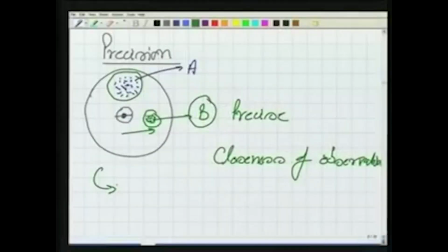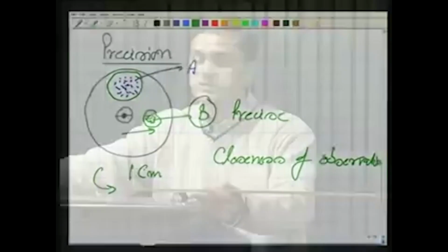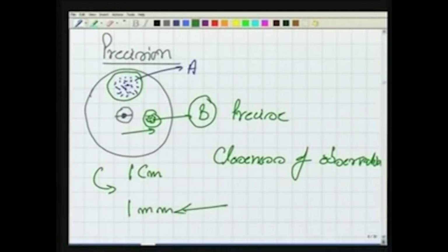Another example, well, in this scale, if the least count of the scale is 1 centimeter, you are trying to measure up to 1 centimeter, and then you are approximating within 1 centimeter. That is case number 1. In case number 2, the least count is 1 millimeter. So now you are confident to measure up to the millimeter, and you are estimating only within 1 millimeter. Obviously, in this case the precision is more.